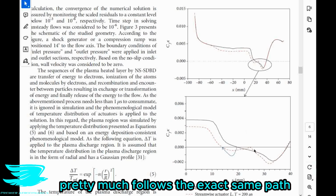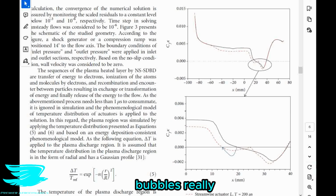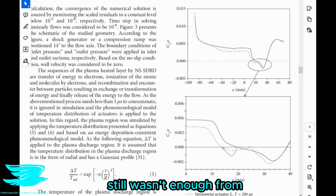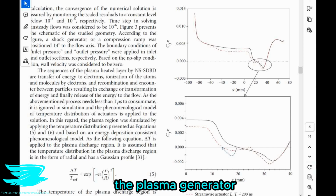And then it pretty much follows the exact same path as the black line. So while it may have had the chance to reduce the bubble length, it just made it longer in total and actually divided the bubble into two bubbles really. The authors say that the flow ended up separating again because the energy in the boundary layer still wasn't enough from the plasma generator. We'll look at that a little bit later with the boundary layer profiles. But in this particular case, the plasma generator effectively did more harm than good in the separation region.